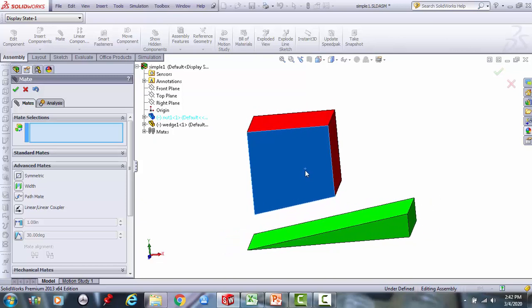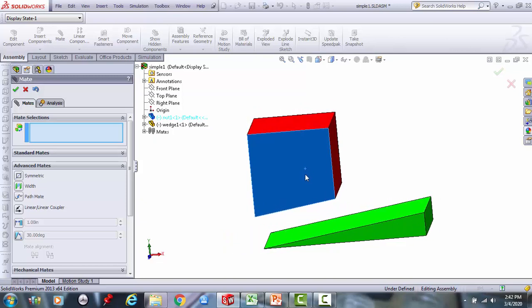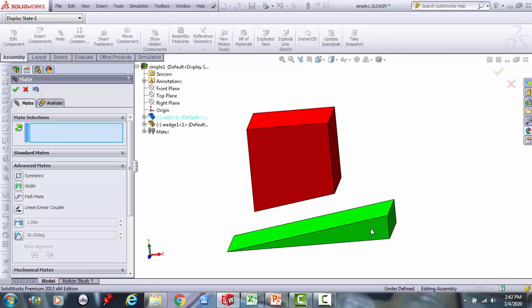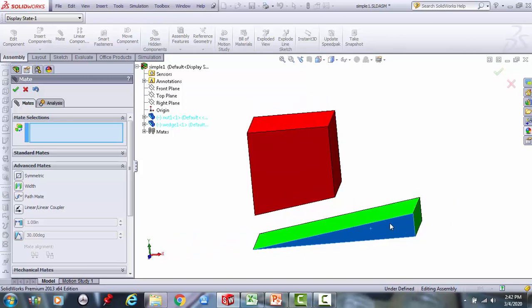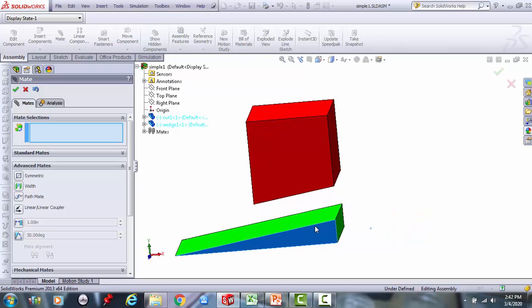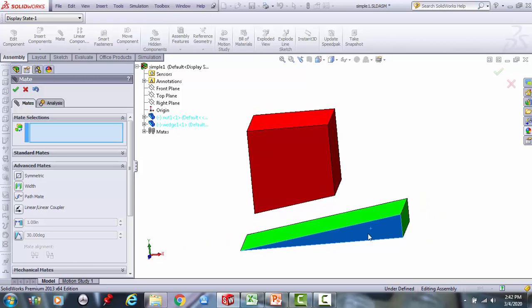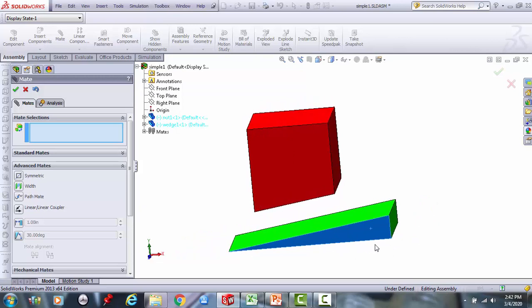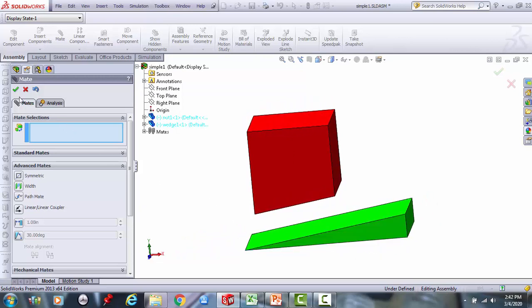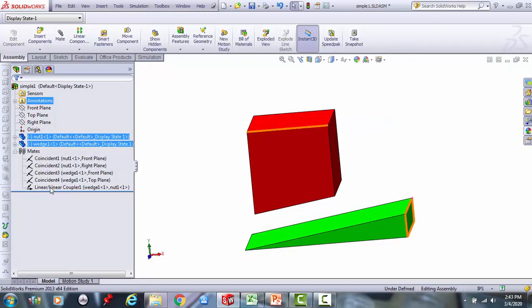So now this looks right. So if I move the nut a little bit, the wedge is moving a lot. Move the wedge a little bit. So if I move the wedge like the distance, I think that's 8 inches, the distance of the width of the nut, then the nut goes up about 1 inch. So I think I'm in good shape now. So I've got linear.